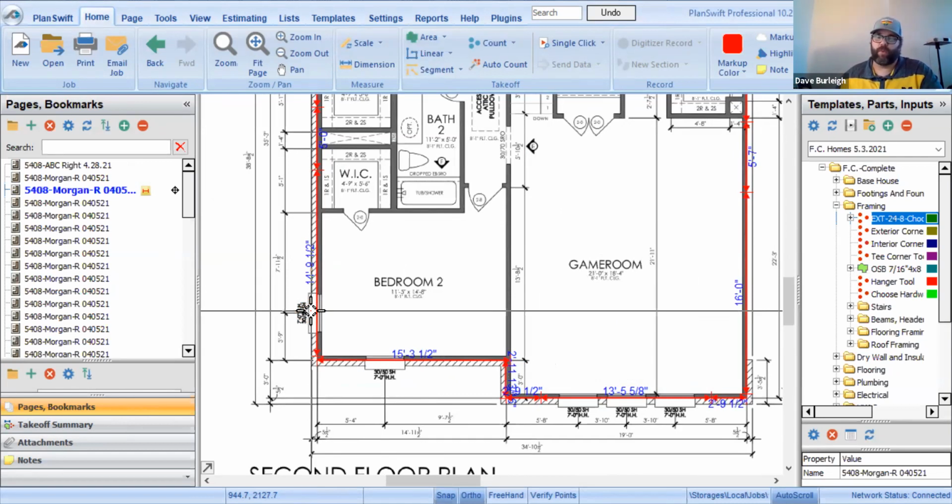We'd love to build every wall at 16 feet. That way we're not cutting our bottom plate. We're not messing with our top plates. We need an even stud count. We don't have any studs that are closer than they need to be. But once we drop down from that, 14 feet 9.5 inches is actually the next size to be able to still say we're not wasting any studs. I don't have any studs that are too close to one another.